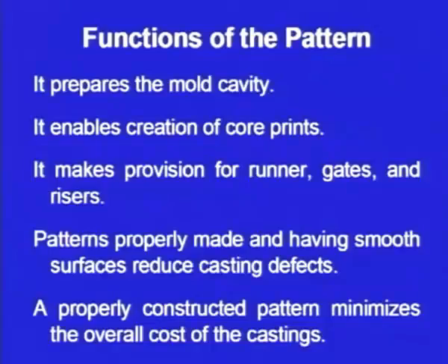And the second function is it enables creation of core prints. Yes, whenever we make a casting in which there is a hole, for that purpose we have to use a sand core. In some cases these sand cores are supported by chaplets. In some cases these cores are supported on the ends. Sometimes the cores are supported on the ends as well as with the help of the chaplets.